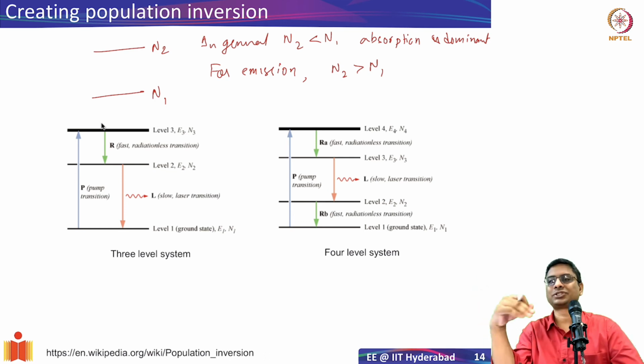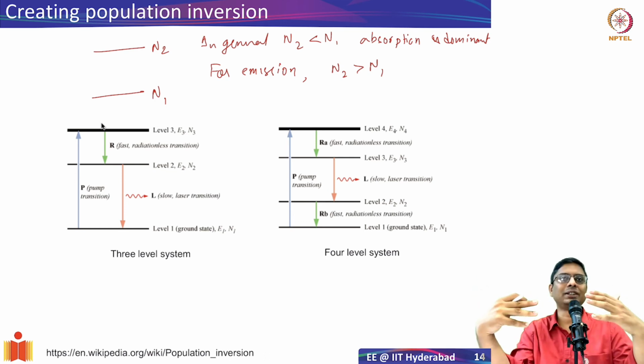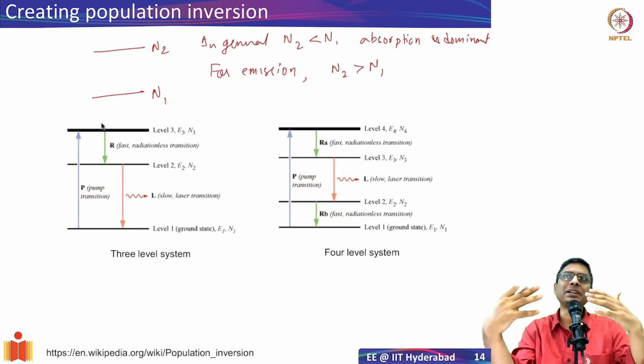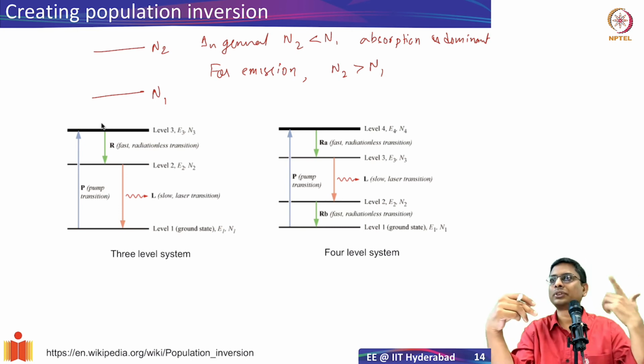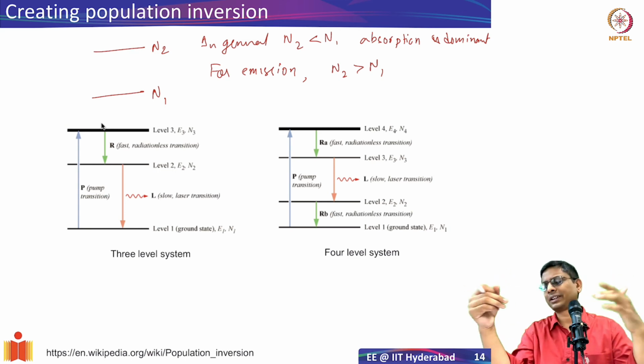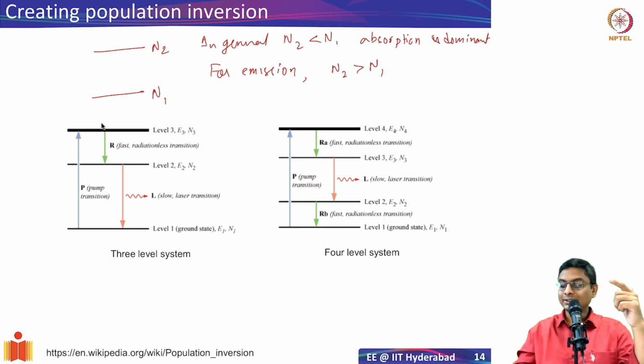We just shined a high energy beam so that the electron goes into a higher level, undergoes thermal relaxation, comes down to the band edge and emits a photon. That's what we talked about, right? It can be pumped optically or even electrically. I can supply electron-hole pairs, and I'll show you in a moment how we can do that. So you can have N2 greater than N1. That is essential. And this phenomenon of N2 being greater than N1 is known as population inversion.